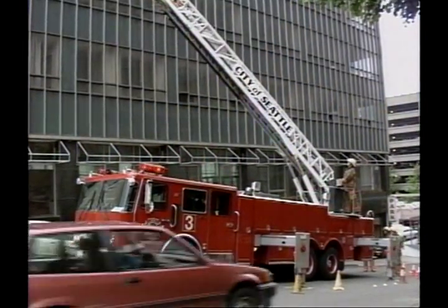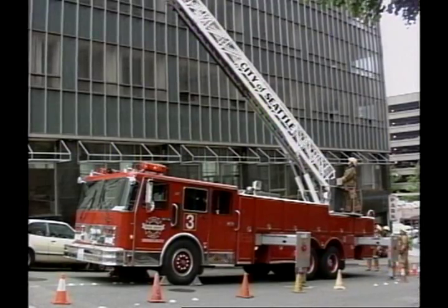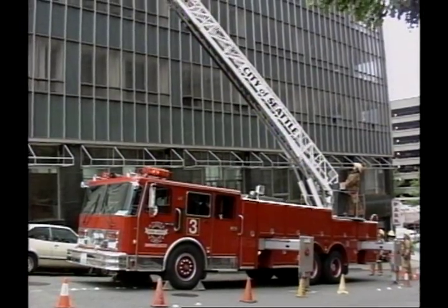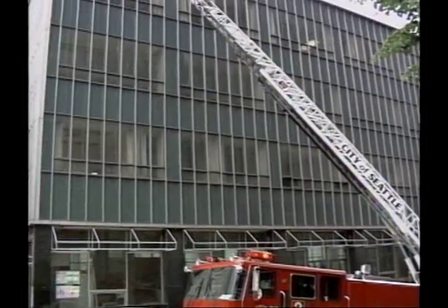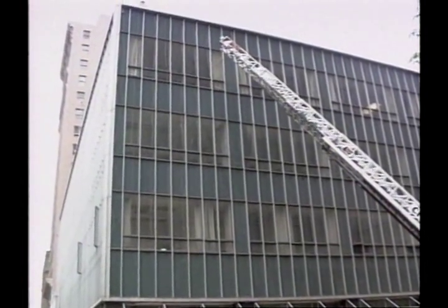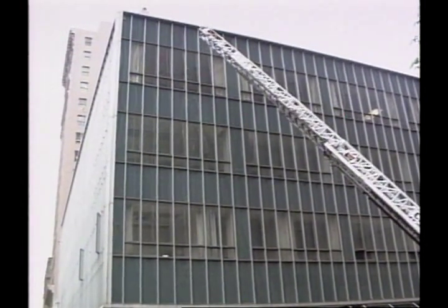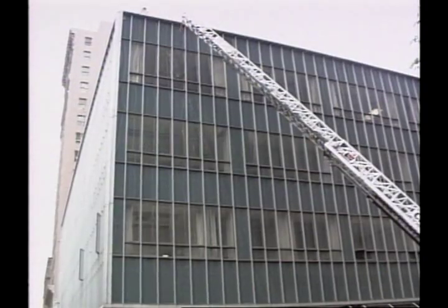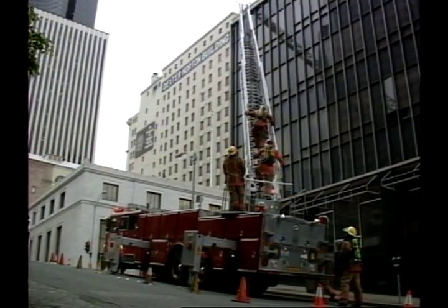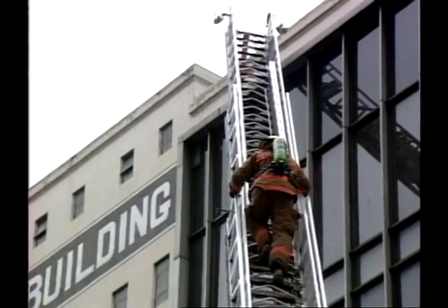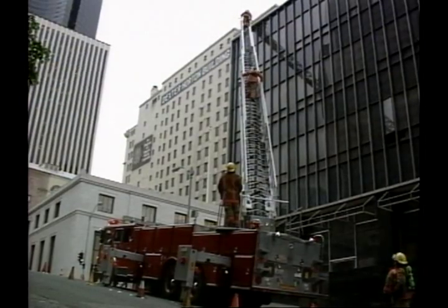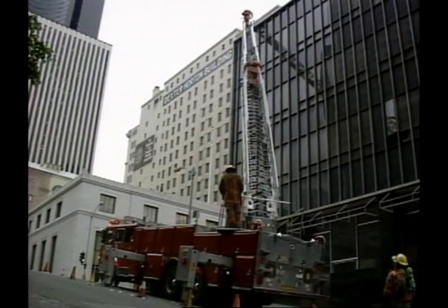Operating on an end-to-end or longitudinal grade is generally more difficult than a side-to-side grade. In this situation, the rungs of the aerial ladder will not be parallel to the ground if the ladder is operated off the side of the truck. When the aerial device is raised and lowered, there will be a twisting force and resulting motion that is very dangerous to personnel working on or around it.